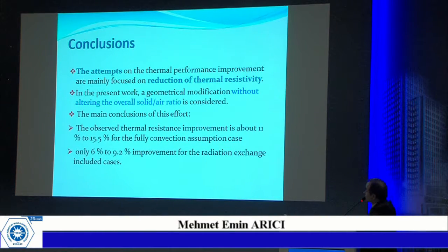We know in the literature, attempts at thermal performance improvement are mainly focused on reduction of thermal conductivity. In the present work, a geometrical configuration without altering the overall solid area ratio is considered. The main conclusion of this effort, as we saw in the resulting graphics, is that the observed thermal resistance improvement is about 11 to 15 percent for the fully convection assumption case. Only 6 to 9 percent improvement is observed for the radiation exchange included case.